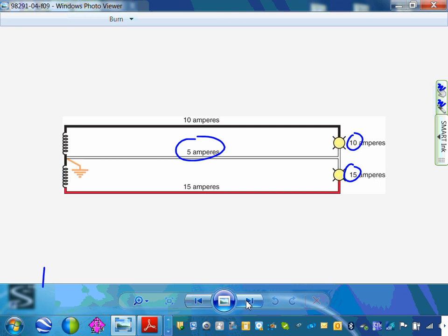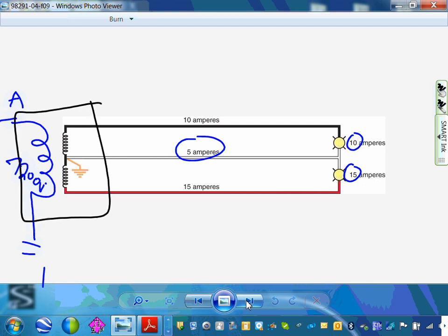Do you guys understand the difference between a single-phase source of power and a 3-phase? You work with utilities. This is coming out of a utility-owned transformer that looks like this. So this is typically 7200 volts, phase A. That's a big transformer in one, the little barrel sitting there, the container. Now, they ground one side, and this is your transformer. Then what they do is they take a phase and they split it. This is called a split-phase power system. One phase, they split it into two hots.